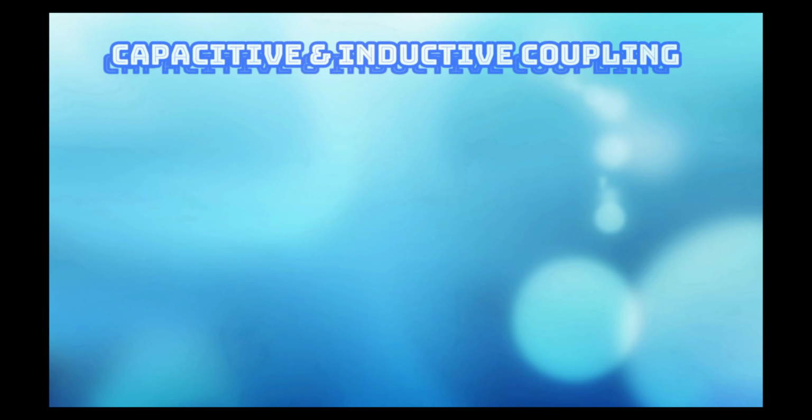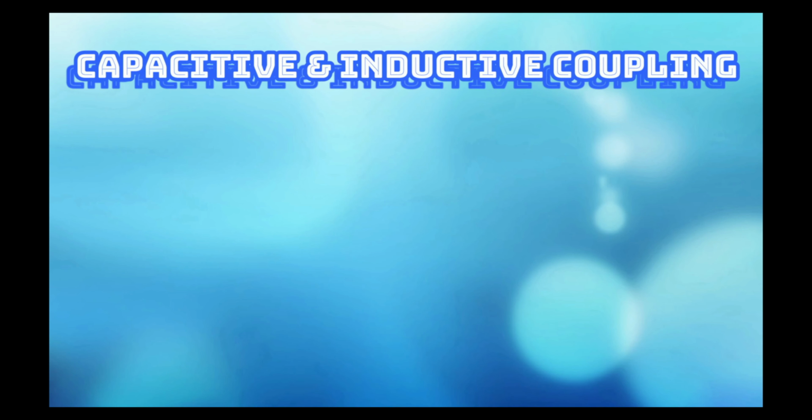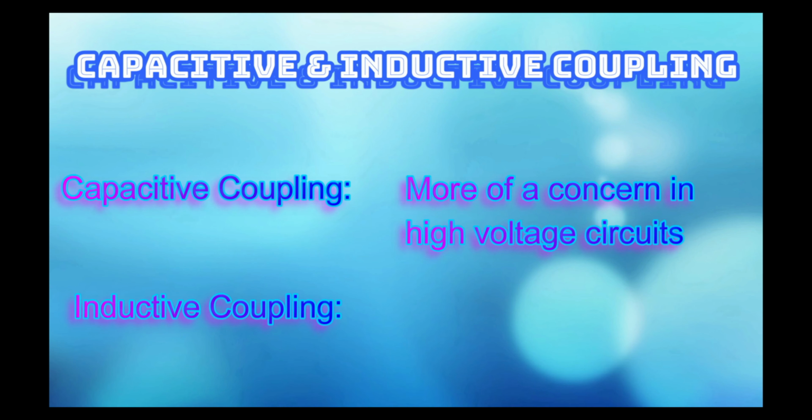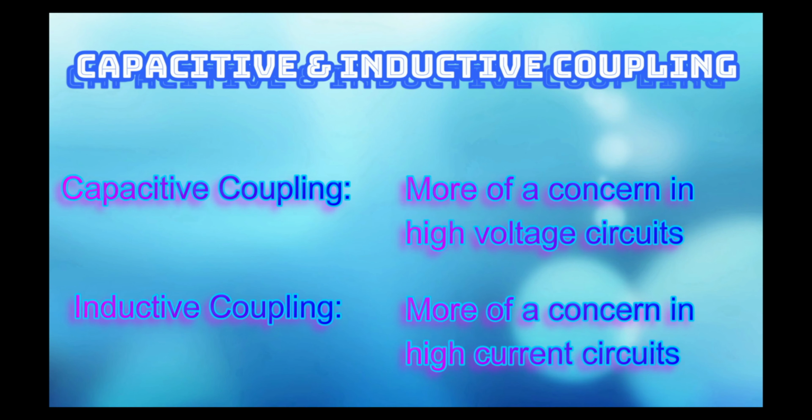With today's increasingly sensitive electronic technology, even relatively low background fields may be sufficient to cause equipment interference. Due to the close proximity of sensitive devices to noisy sources, the leading modes of EMI are capacitive and inductive coupling amongst cabling and harnesses. Capacitive coupling is more of a concern in high voltage circuits, while inductive coupling is more of a concern in high current circuits.